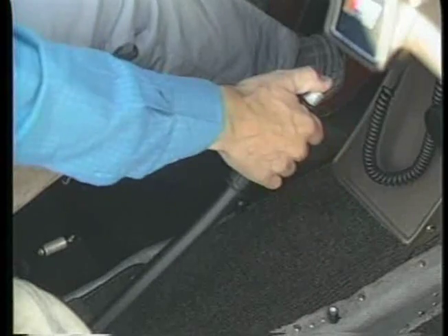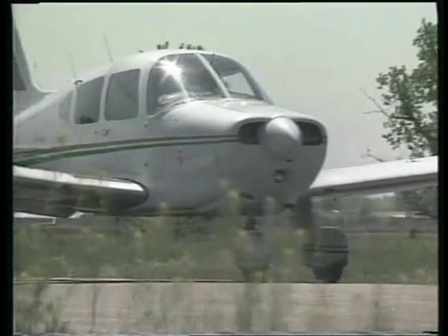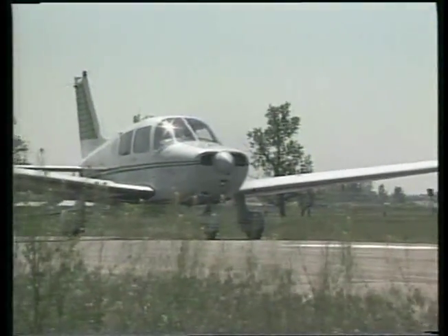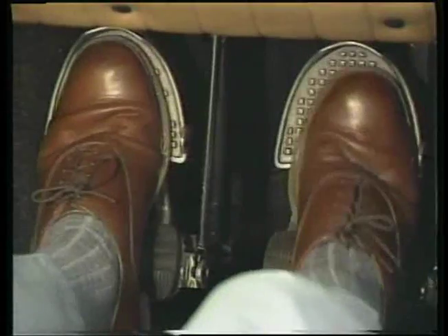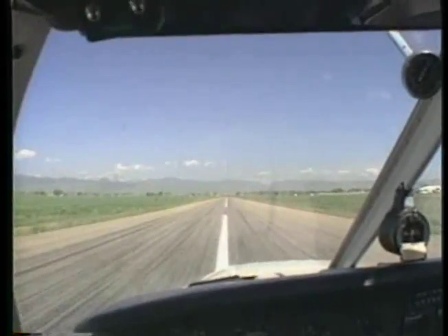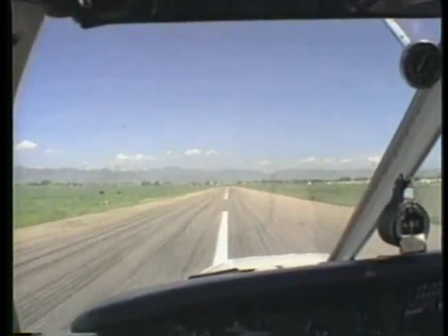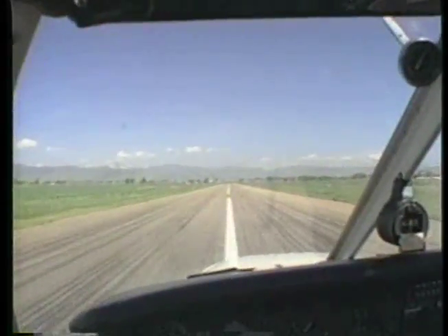The pre-takeoff checklist is basically the same as the one you use for a normal takeoff, except that you set the flaps as recommended by the airplane manufacturer to achieve a maximum performance climb. If runway length is critical, position your airplane so that you can use all of the available runway. Then, align the airplane with the center of the runway and initiate the takeoff by holding the brakes and applying full power. While this does not necessarily shorten the ground run, it does help you be sure that the engine is running smoothly. During the takeoff roll, allow the airplane to accelerate in a level attitude with the elevator in the neutral position for minimum drag.